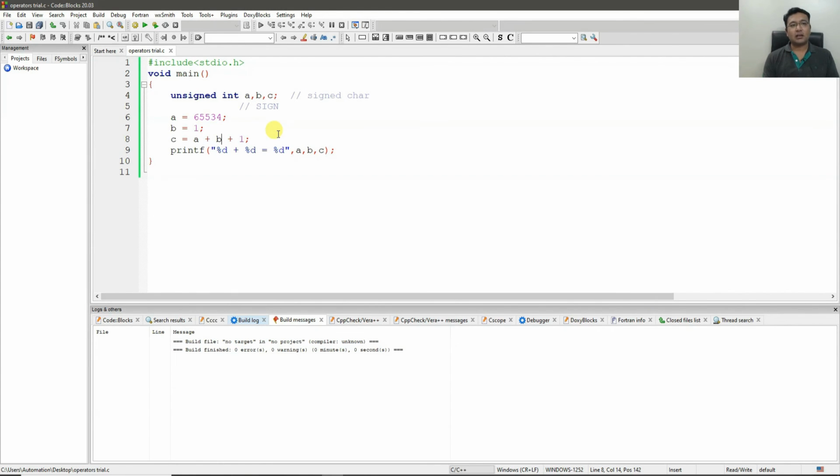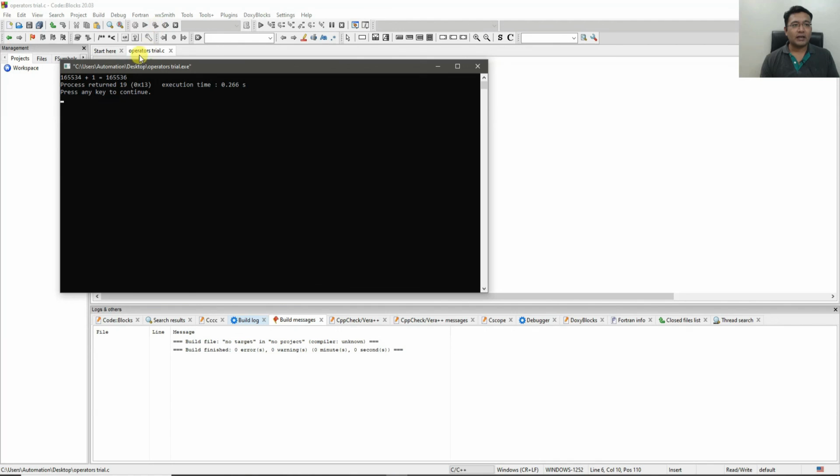On embedded compilers, int will always be 16-bit wide. Here it may be a 32-bit number. Compilers will act differently on different computers. So on a PC, int is not just 16-bit but a 32-bit variable.